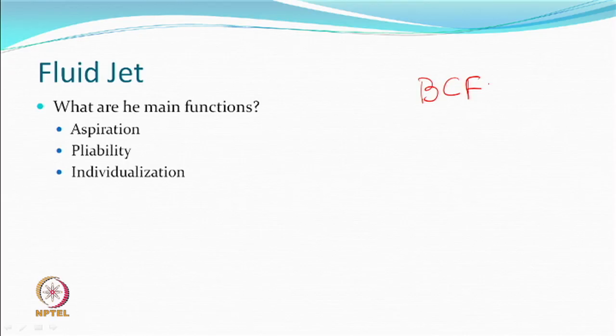If temperatures are low or not hot, then obviously the larger bends are going to be made. And of course, this is the most important expectation, that individualization of the filaments. So, it has to be used in a manner that the filaments are not only sucked and thrown out, but they are individualized also. Only then will you get that structure.